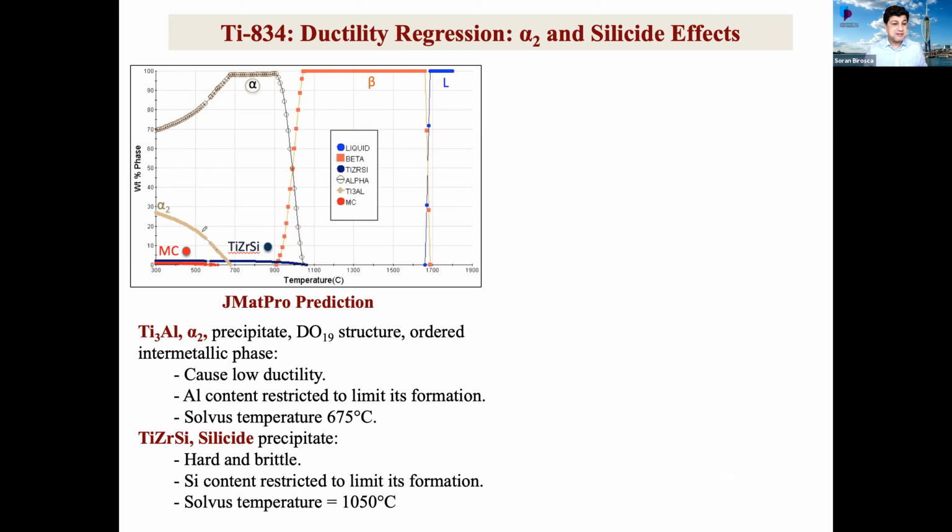We have, for example, the carbide, which will be dissolved at around 570 or something around that. So if you heat treat it and then quench it, you're removing the carbide. You can assess in the same condition what effect the carbide has.